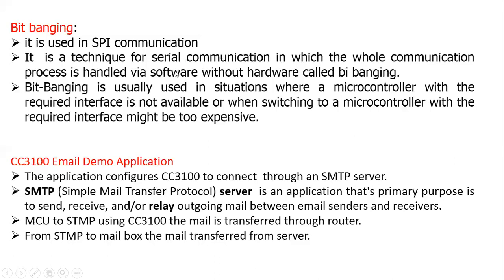So without hardware, if you are running the SPI module using software, then we call it bit banging. Bit banging is mainly used where a microcontroller with the required interfacing is not available. That means hardware is not available, and also it is more expensive.